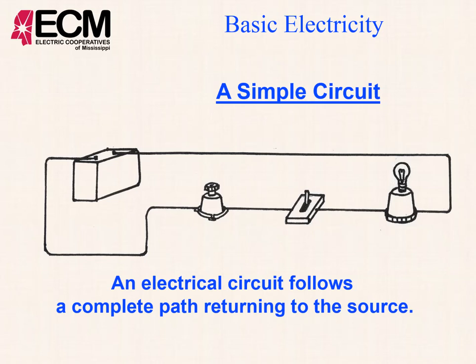The battery is the source. So we have all this. This is a fuse, that's a switch, and a screw-in light bulb that's screwed in, and it's wired up in series. So actually you have one wire here. Okay, it's one wire going from here all the way around back to the other side. And here it hooks in. The electrons will actually go up through the bulb, across there, and back down, and back around to the other side. So with the fuse in, switch closed, and light bulb screwed in, we attach it to the source. I think we can all agree that the light bulb will come on if the circuit's intact, it's complete.